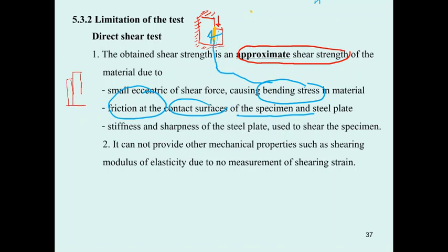And then you fix these two to the bottom plate. Okay, and then you have this. And then you put the specimen, okay, cross them like this. That is going to be a specimen, and then you pull this. So there is some friction occurring at this point, okay, and that may cause some deviation of the result from the direct shear test.